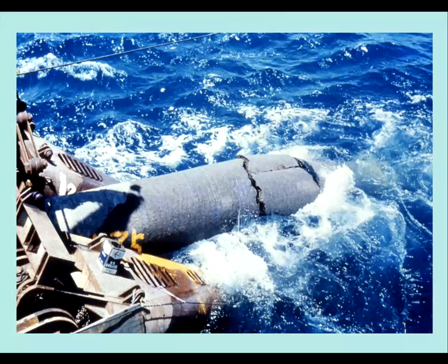But what happened is this stinger was a buoyant stinger. It was filled with air. And it ruptured. Filled with water. And of course then it went like that, and the pipe got overbent, broke. So this was a bending failure, and collapse of the pipe.